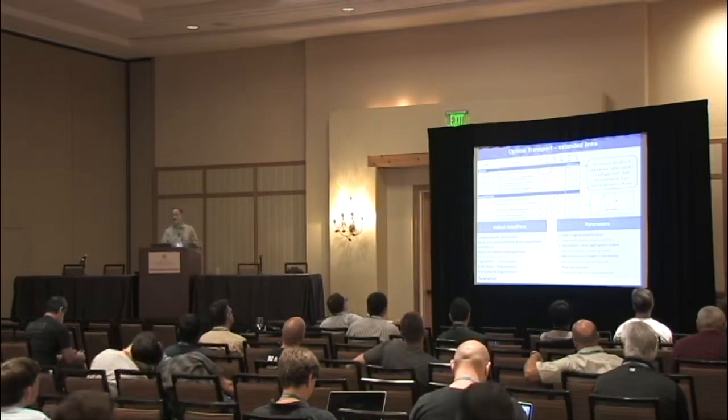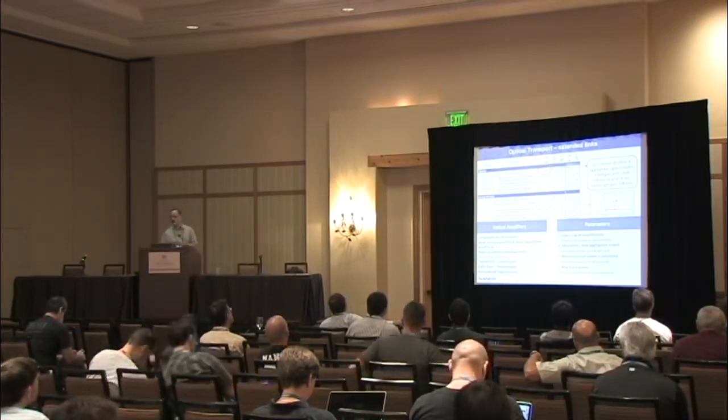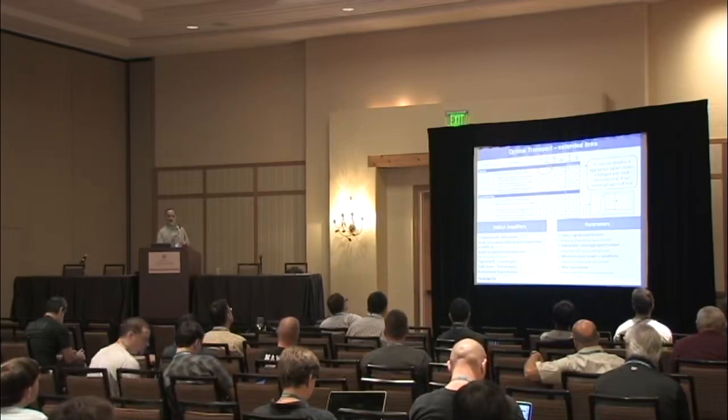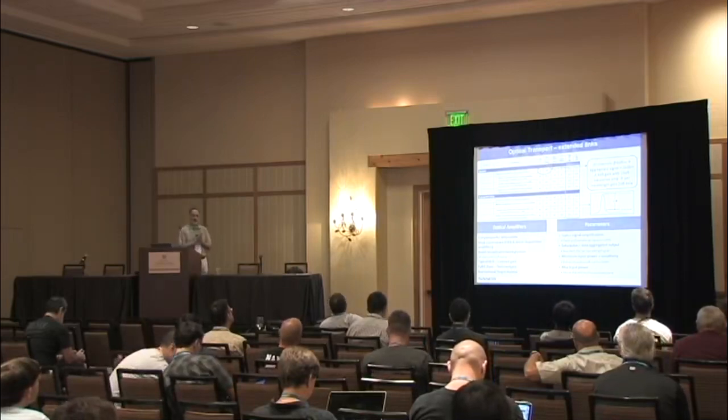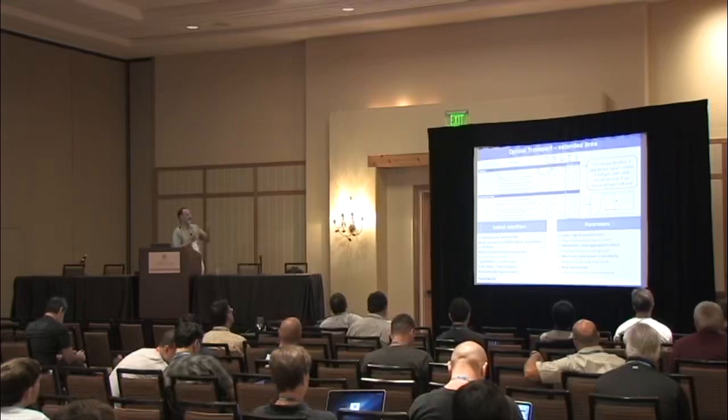So regardless of how many wavelengths you have and what your gain is, you are going to saturate. That's the maximum output that you are going to get out of this amplifier. So that may limit the per wavelength gain. And I have an example there.